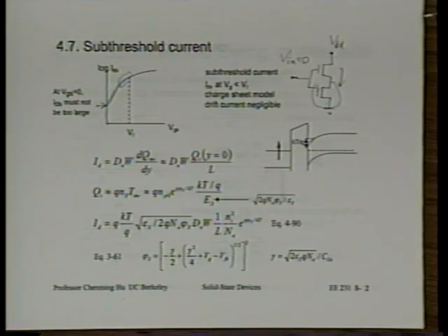It sort of seems like the way that you state that VGS, IDS must not be too large, that there's a mathematical reason that has to be, but it's purely for power conservation? That is purely for power conservation, all right? At least that's the first trouble we're running into if it becomes too large. Of course, if it gets eventually very, very large, then beyond power, circuit functionality will be affected. That is, you cannot ever tell whether the transistor is on or off. How can you use it as a switch in any circuit function? But right now, we're concerned about it because it's a power consumption problem. All right? One more question?